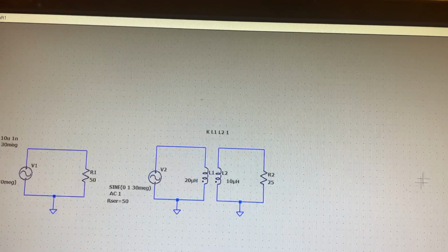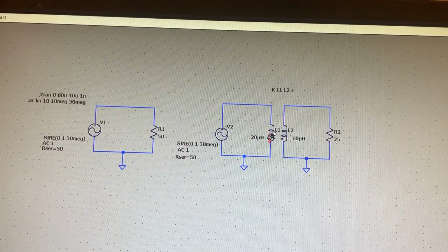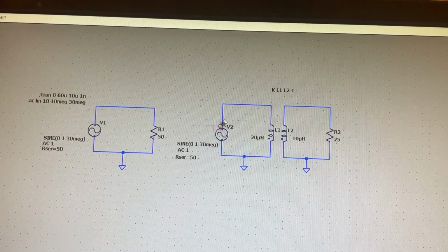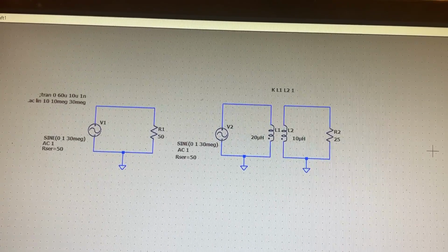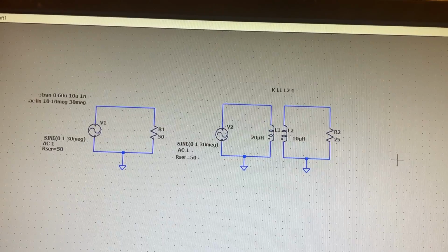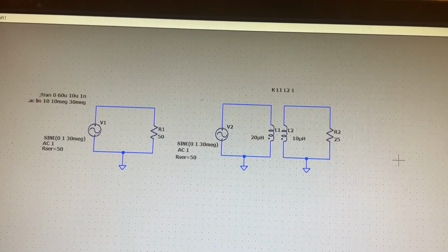How we use the turns ratio of the transformer, which then determines that turns ratio squared equals impedance ratio. And we use the impedance ratio to do the impedance transformation. And we can do that when the source is lower or greater than the load. So I hope this was helpful. I hope you have a better understanding of how transformers are used and how we use them in RF circuits to transform impedance. All right, RF Man, thank you very much.